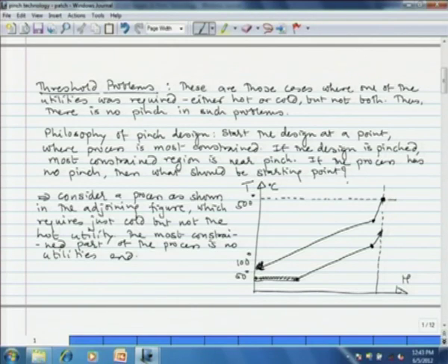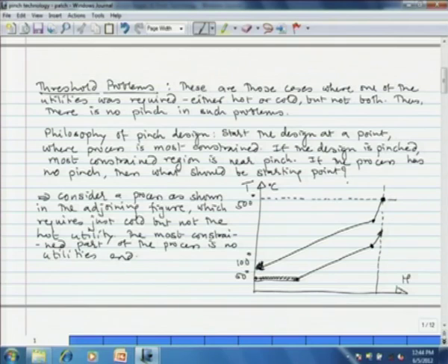We have already seen threshold problems in previous lecture. Threshold problems are those problems in which the temperature or the enthalpy is matched at one end of the problem. That means, you do not require either hot utility or cold utility. Like the one which you see on the screen now is that one which requires no hot utility, which means all required temperatures of cold streams are met with heat absorption from hot streams.